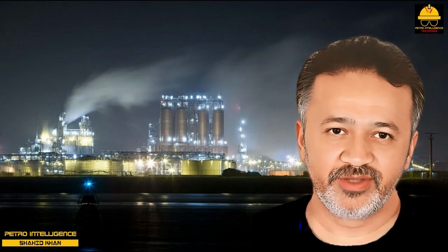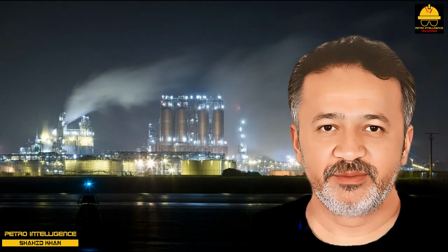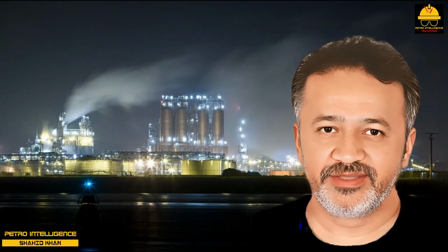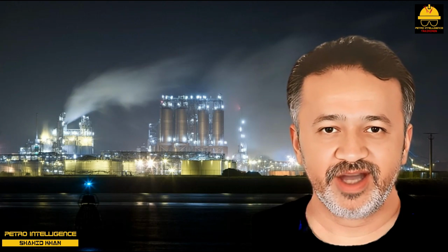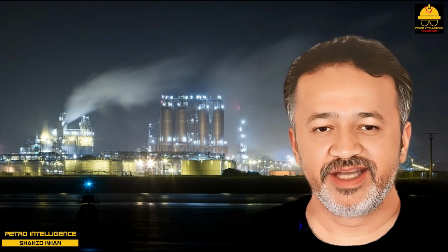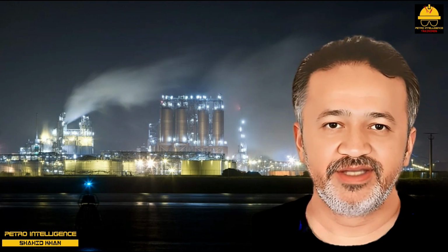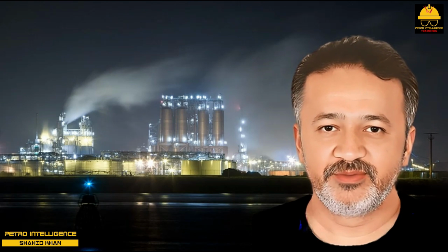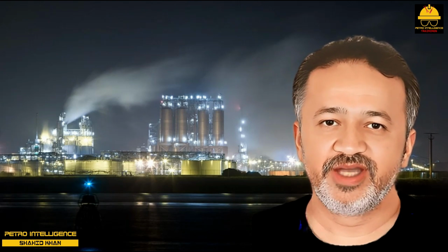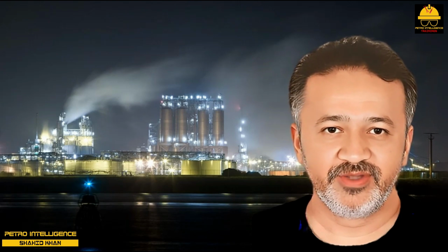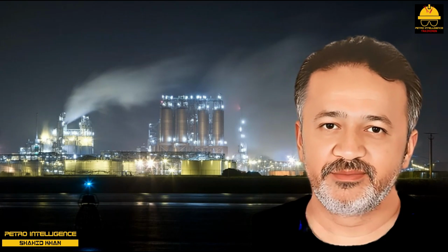2. U-tube bundle. The tube side of a U-tube bundle can be cleaned, including the return bends. The problem is not tube side cleaning, but tube side inspecting. There is no practical way to see if the tubes have actually been hydroblasted clean. While a U-tube exchanger is less expensive than a conventional floating head exchanger, 10 to 15%, it should not be used if tube side fouling is a factor.